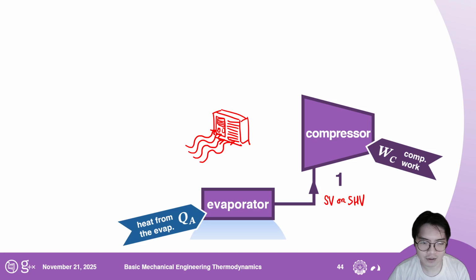Why? Well, now the goal is, okay, congratulations, you have now absorbed energy from the cold space. What are you going to do? Are you just going to hold on to that energy? Of course not. You need to find a way to throw it out. But normally you're supposed to throw it out to the cold space because, well, you reject heat like that. How are you now going to throw it out? You're now going to throw it out in reverse, to the hot place, to the ambient air outside.